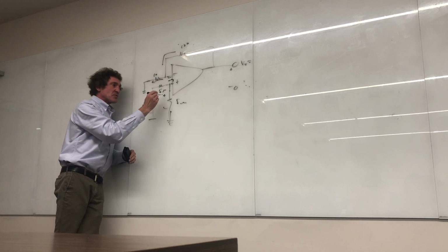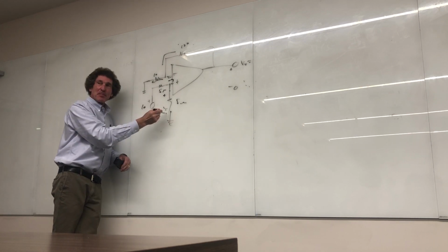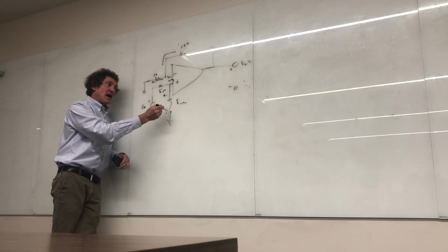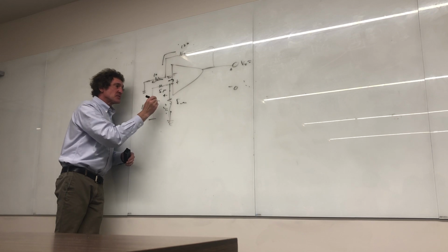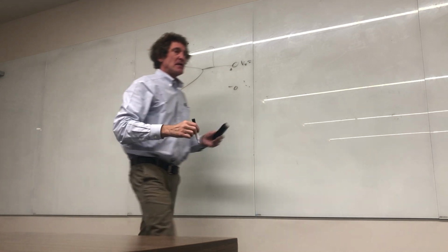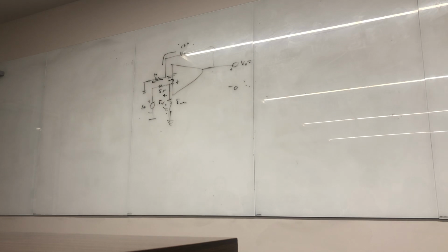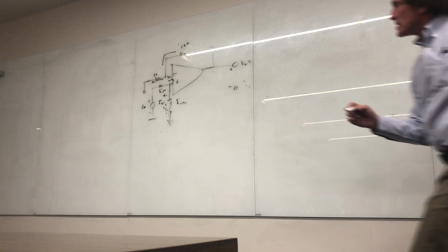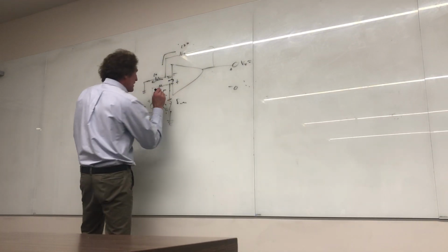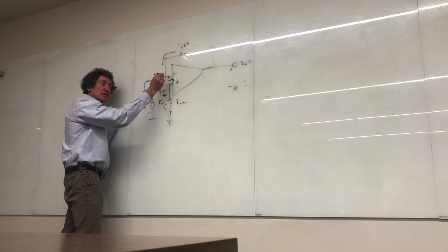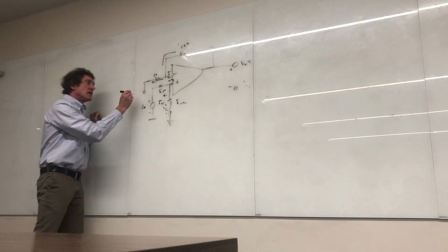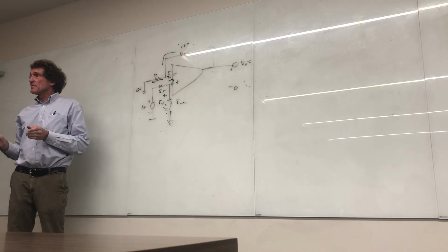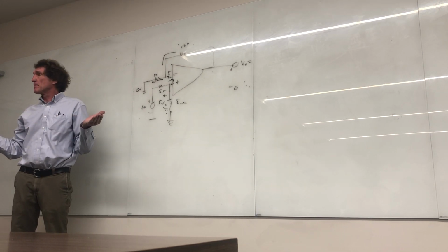What's the voltage across the 5 ohm right here, from here to ground? It would be 5 over 5 plus 5, or 1/2, correct? Times 10, or 5 volts. So there's really plus to minus 5 volts there. So if I have 5 volts right here, what's the voltage here? 5 volts, right? What's the voltage here? 0, correct, class? Ground is 0, correct?